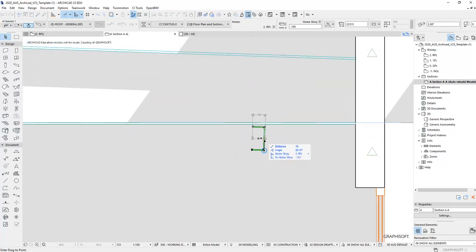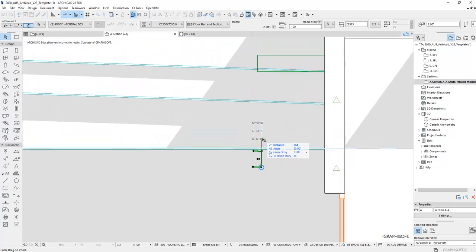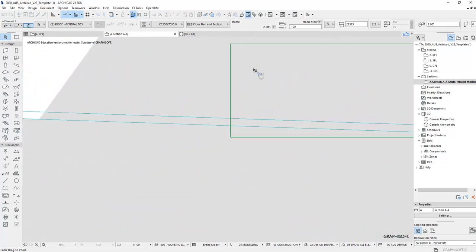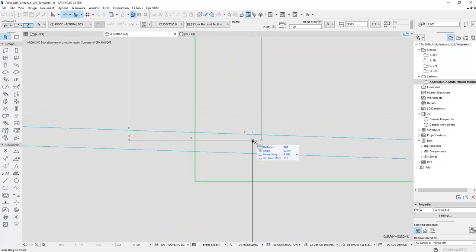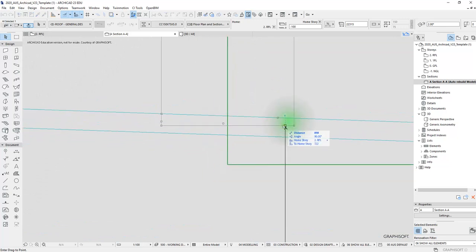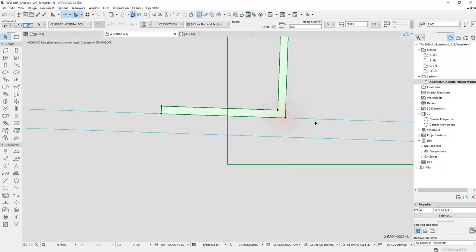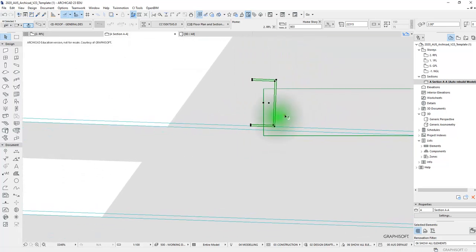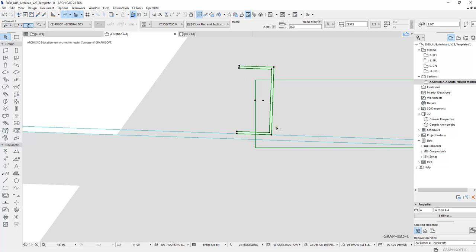And then I'm just gonna make sure I hold Shift when elevating this. Right, and after that, I will need to make sure I do my last click where the intersection is, like this point here. Done. See, this is now perfectly sitting at 2-degree pitch.